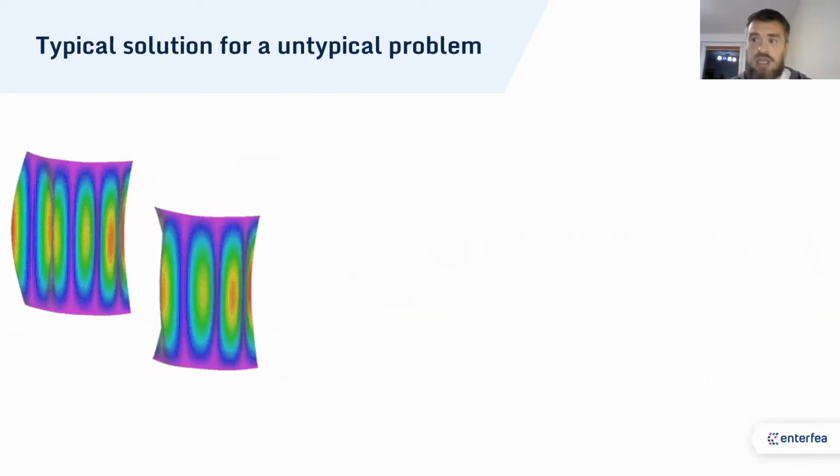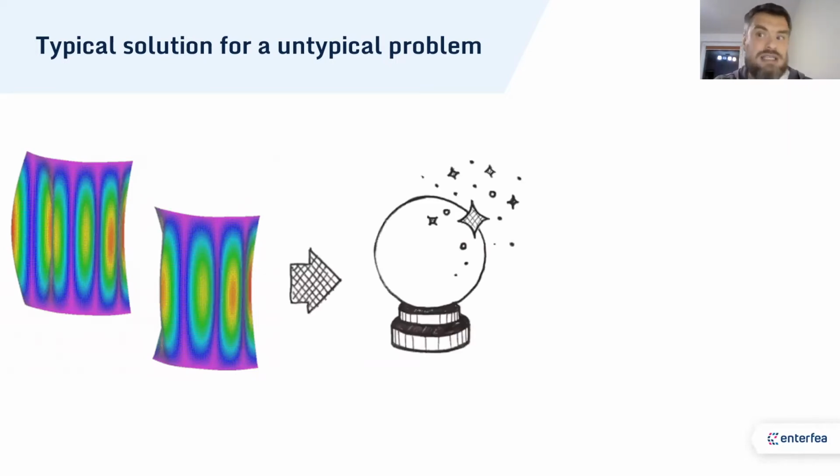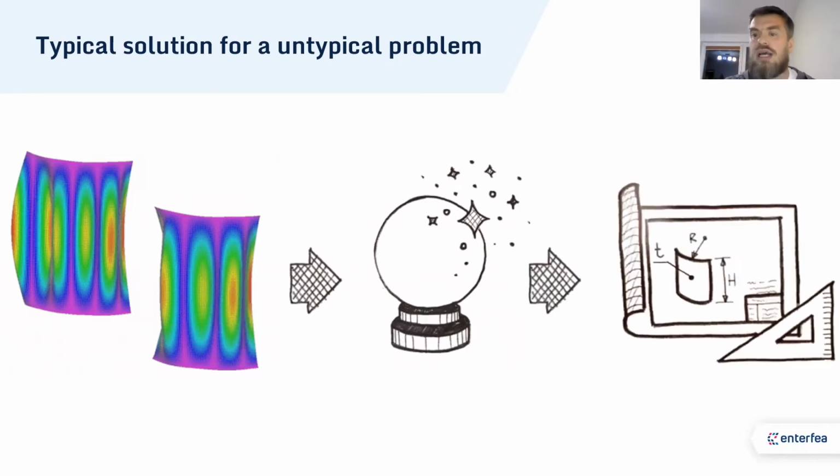And the problem is that, okay, let's do linear buckling. And again, just as with stresses, you have to guess. I get an eigenvalue from linear buckling. It may be 1, 2, maybe 4. And you have to guess, am I willing to accept it or not? And based on this guess, you are making a design. And I don't know about you, but I don't like guessing at all.